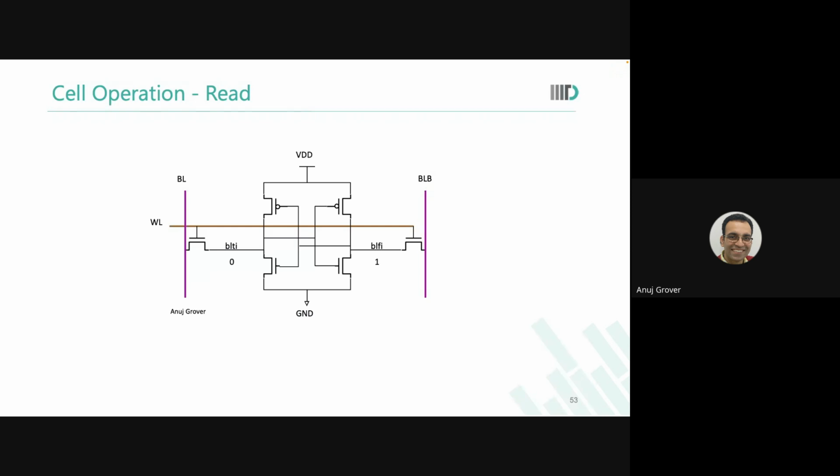This is my 6T memory cell, and we know that to be able to read the memory cell, to be able to access it, I will need to take the word line to 1. Are you with me on this? But I do not just take the word line to 1 as is. Before I take the word line to 1, I will precondition my bit lines. They will both be pre-charged to a predetermined value. I'll charge them to a predetermined value before the word line comes.